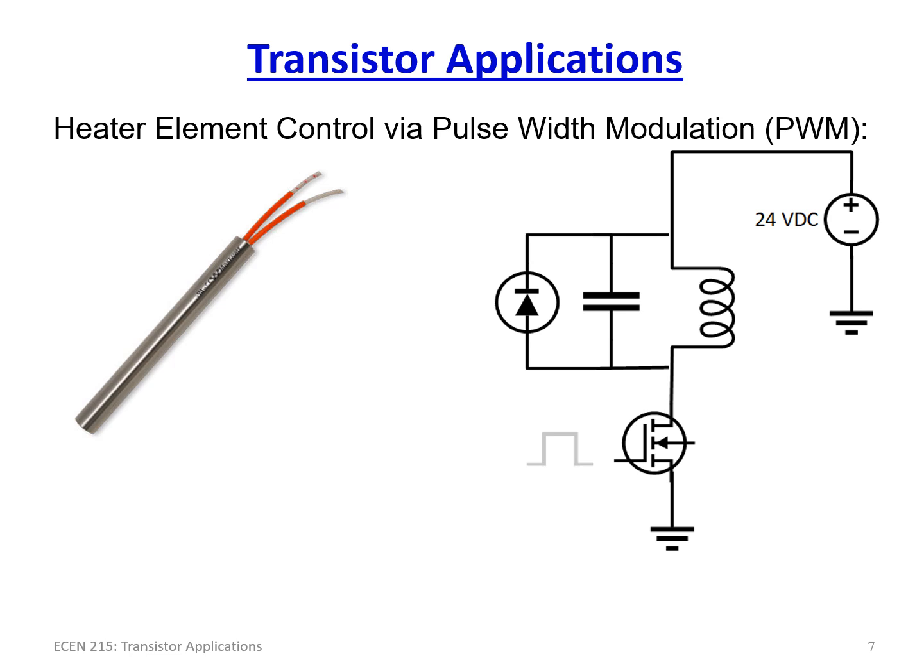Now for heater control, it's kind of the same thing that we've had before. We also notice the same thing exists here. I've got my little snubber circuit. We use the exact same circuit, but instead of a solenoid, it is now a heater element. Now, if this was a resistive heating element, you would not need this. It's only if you have an inductive heating element or inductive type of load that you need to make sure you put this. This is also true on a relay, by the way. So all of these circuits apply.